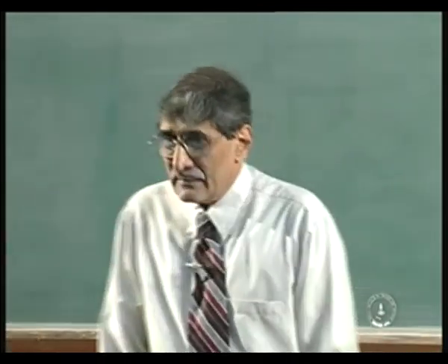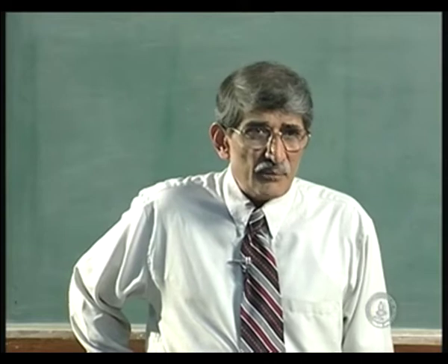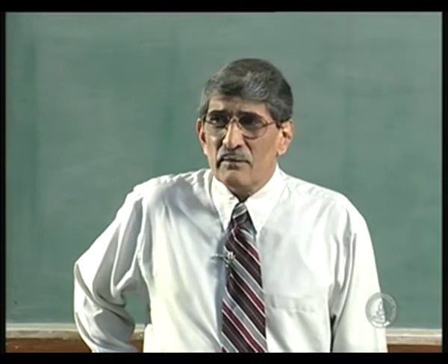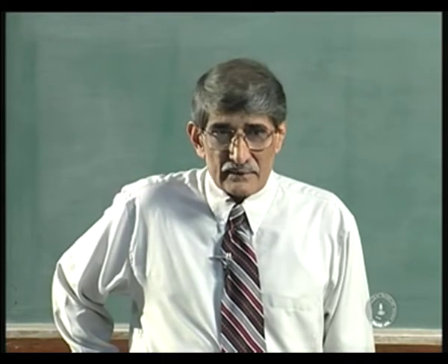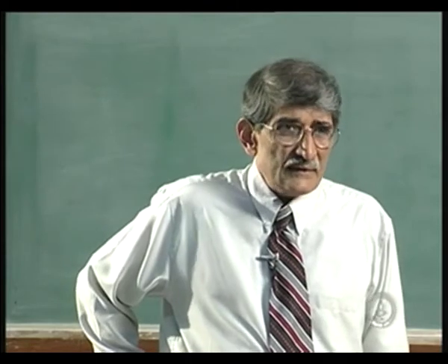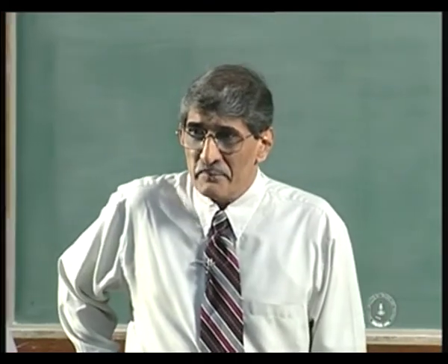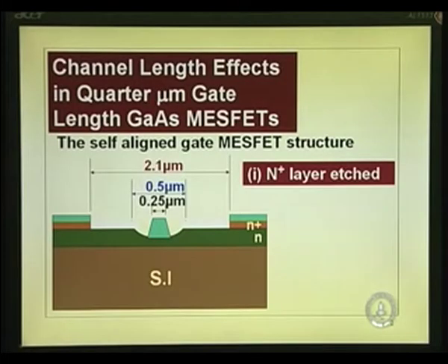So, we have been discussing the MESFET characteristics, taking into account the velocity saturation, and we have analyzed it, and finally, we were comparing some of the experimental results that people have reported. One result that we saw was the change in the gate length, and there we saw the pinch off voltage changing unless you change the thickness. Then we took a look into the channel length effects.